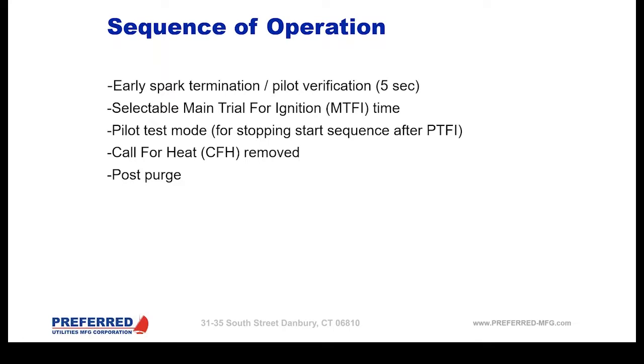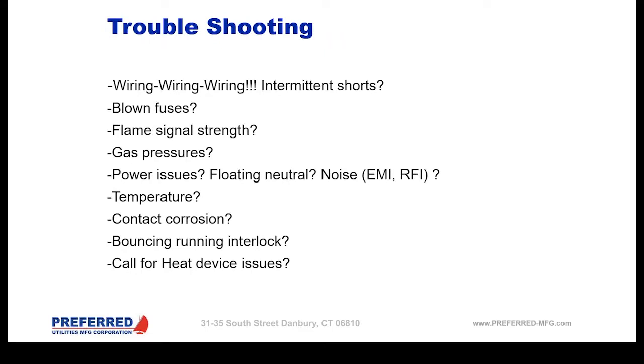Pretty simple process, but a lot of monitoring is required and a lot of safety checks are occurring continuously. Now, troubleshooting. What's the number one problem usually? It's wiring. There's no doubt about it, regardless. And you will hear from many people, oh, it's been running fine for years. Well, that's fine. But intermittent shorts, something's come loose due to vibration, someone's changed something. We don't know, but it is wiring so much of the time.